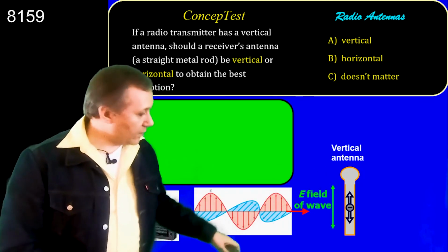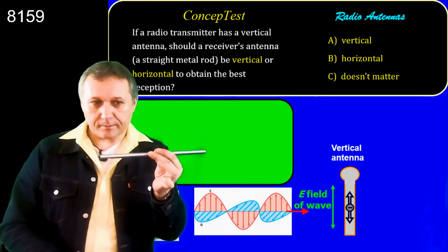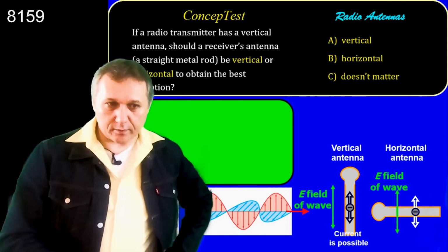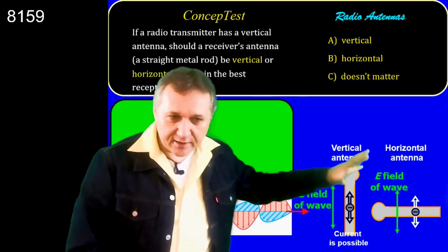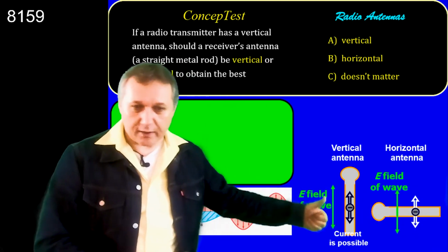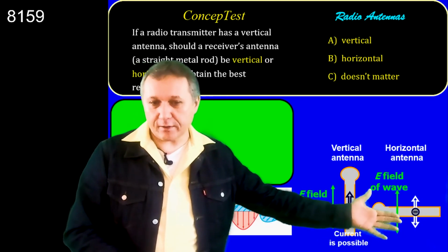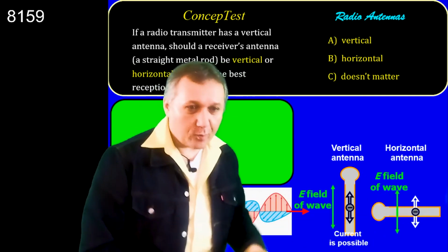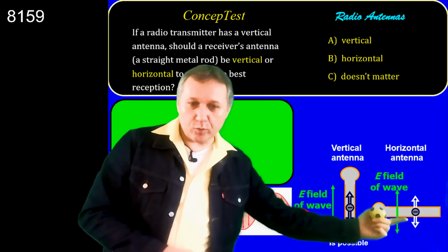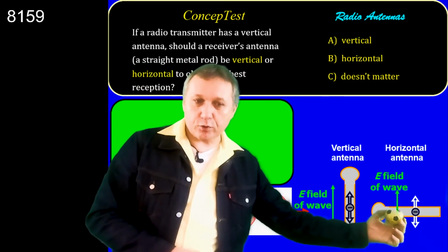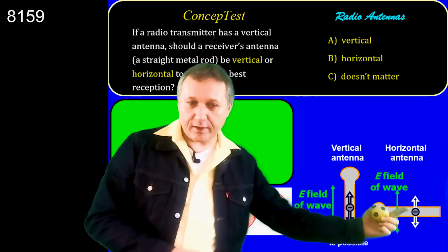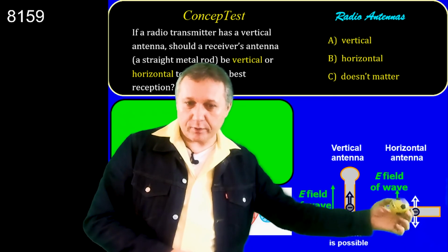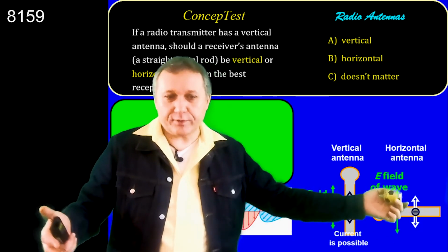But now let's position our antenna horizontally, like this. It's still the same antenna, still with tons of free electrons, and those electrons feel the electric field and will start running. But once they try to move up following the electric field, very soon they hit the edge of the antenna, the ceiling, without being able to move significantly.